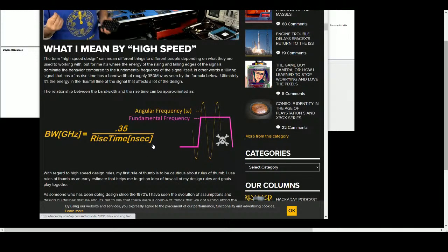We ignored it and did series termination resistors. So we knew we were sinning, but we went ahead and tried to absorb the reflection with anything from 22 ohms to 68 ohms. And we still do that. Yes, we do. Because we can't always. And Bill, something I never understood.